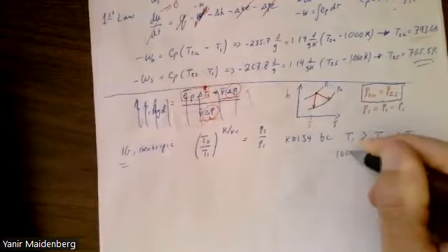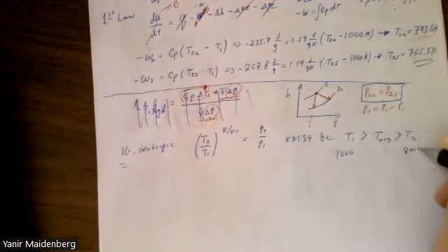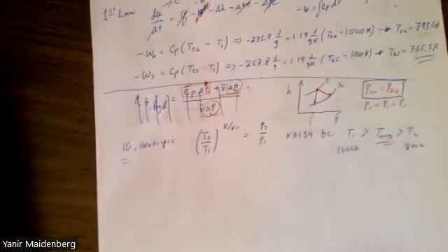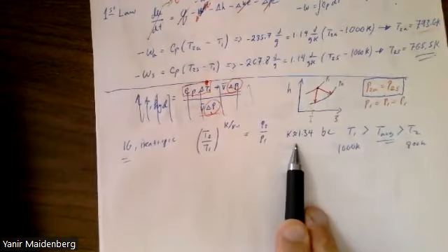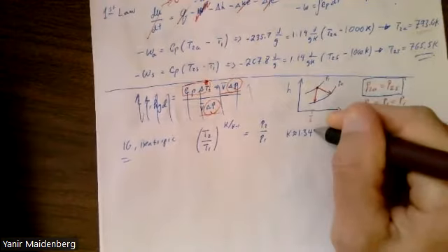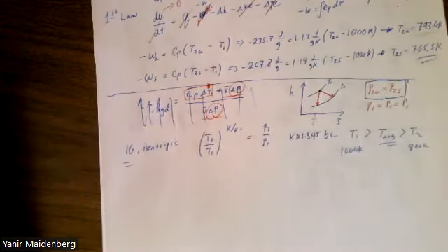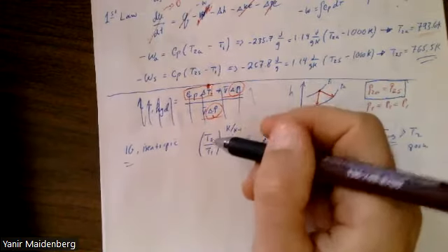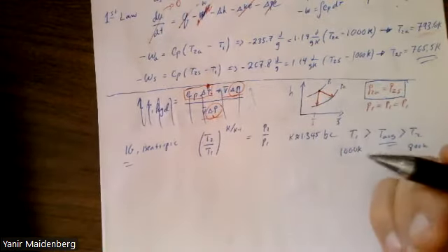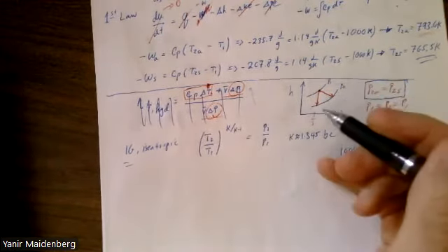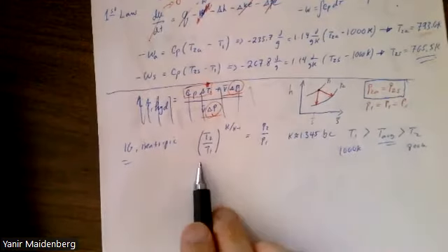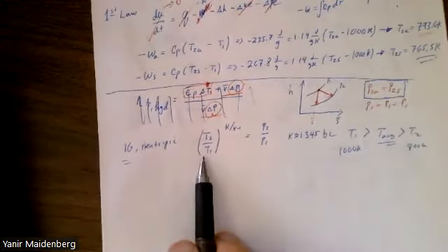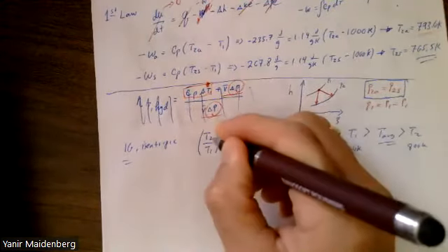So we have 1,000 here and about 800 here, and we saw that the K around 900 is about 1.35, something to that effect. Okay, so whether I'm using the isentropic or not doesn't really matter. Sorry, no, you have to use the isentropic because it's an isentropic equation. So we must use T2S here.